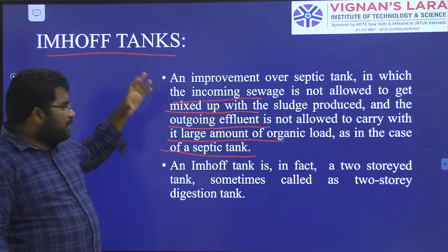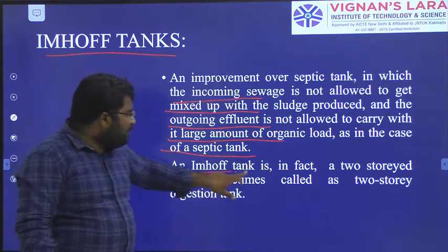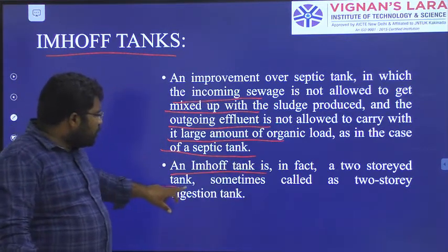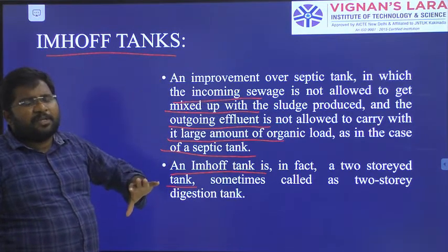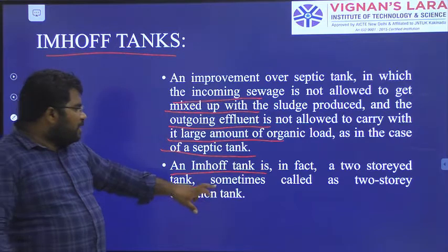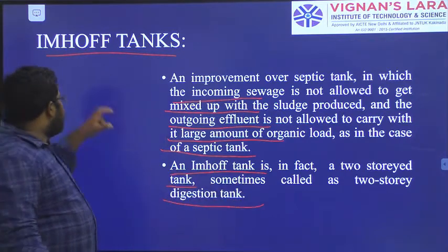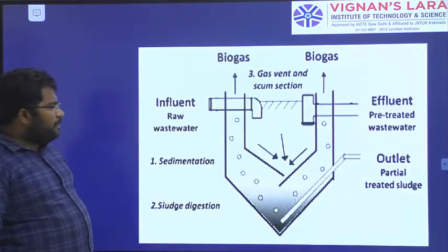We are not going to mix the sludge with the incoming water. It gets separated. An Imhoff tank is in fact a two-story tank. First story will be sedimentation, second story will be the digestion tank. Sometimes it is called a two-story digestion tank. You can see the picture here.